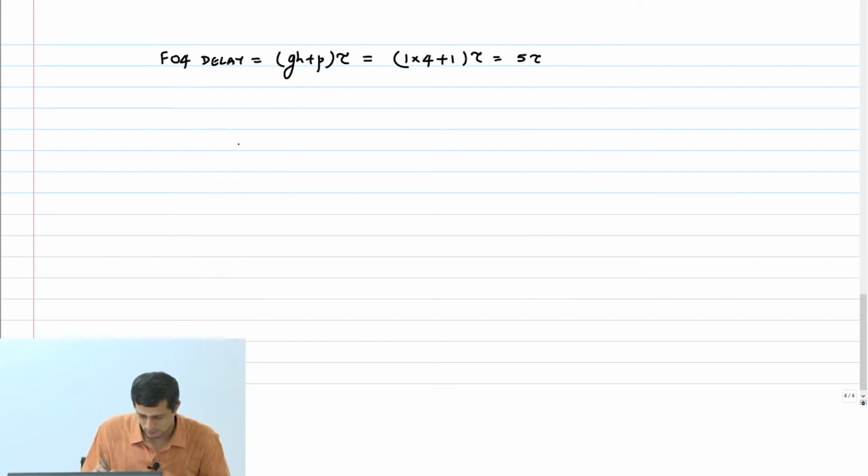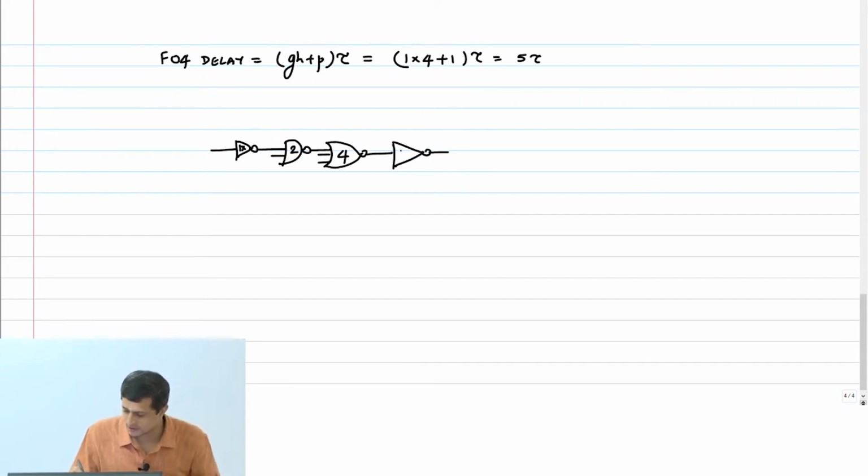So let us now take this expression that we derived and just try to calculate the delay of a path, because next class I would like to start the path delay optimization. Okay, I am saying this is 1x, 2x, I will say 4x, this is a NAND 2, this is a NOR 3, and ultimately I will drive it by a capacitance which is 64x.